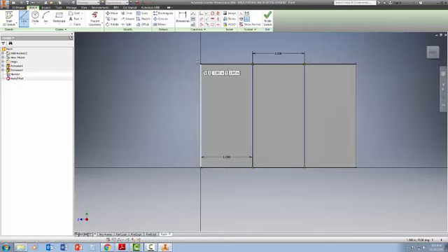Now what I want to do is, because we know we're going to have a problem extruding it because it's on a different sketch, is just go from corner to corner. So watch. Top left corner, click. Okay, I have my line tool. I'm going to drag this all the way across. Drag it to the other corner, click. Come down here to this corner, turns green, click. Come all the way to this corner, turns green, click. And this corner to this corner, turns green, click.